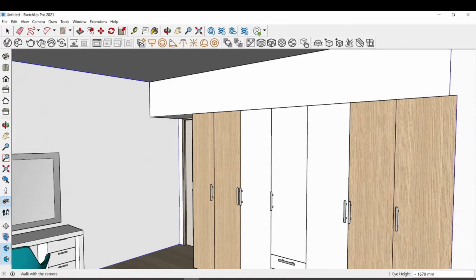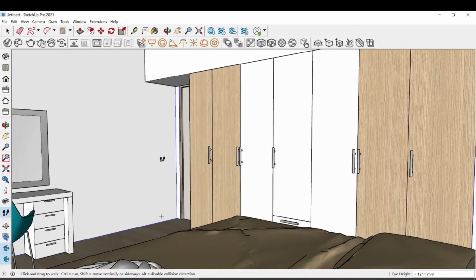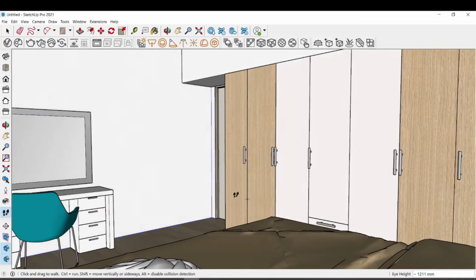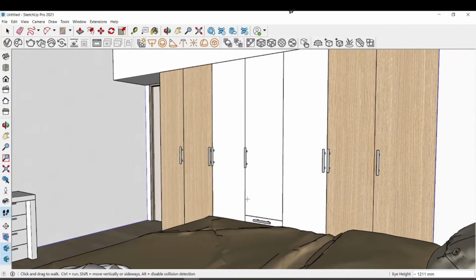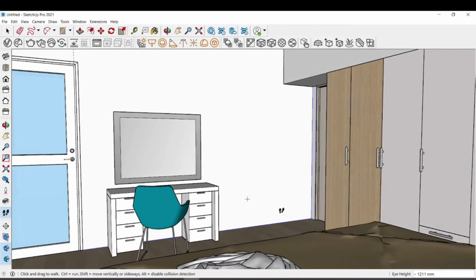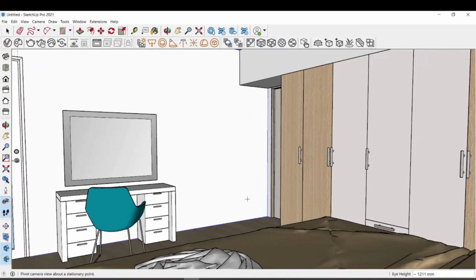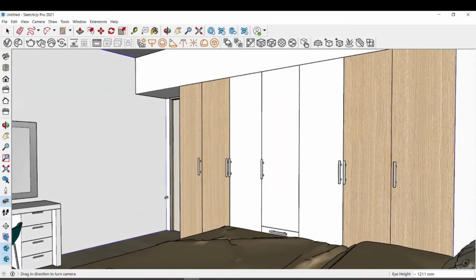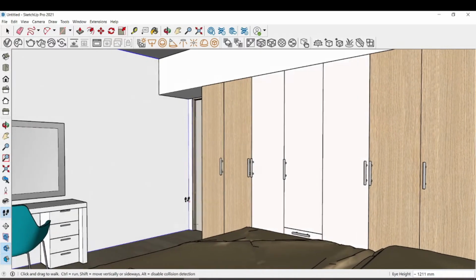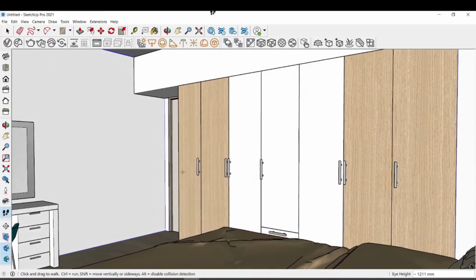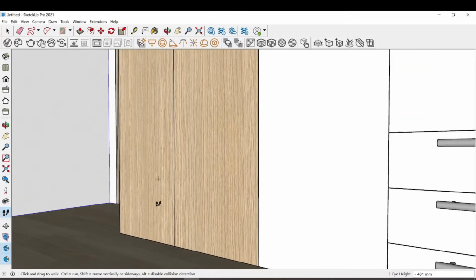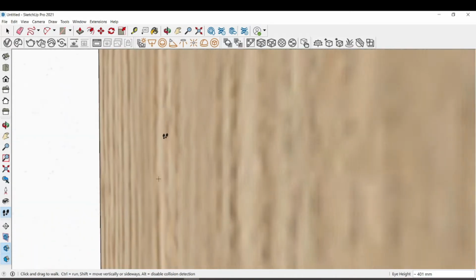Let me now consider the tool with which I can take a virtual walk, the Walk tool. I click on it and you see that I get a pictogram through which, when I click and hold the mouse up or down, I can change the position of the picture and virtually walk around the room. With this tool, I can't go through the walls, unlike the Look Around tool, but I can go through objects, tables, chairs. The higher I pull, the faster I move.